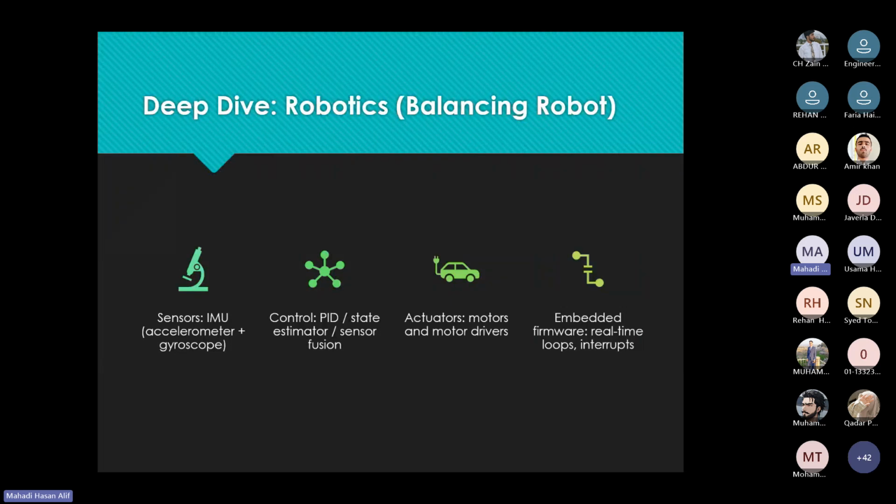The first kind is the values of the linear force on three axes, x, y, z, and the second is the velocity in the rotational axes, x, y, z again. So you get 3 plus 3, total 6 data, and depending on the frequency you're using, maybe 1 kilohertz, it means 1000 times 6, 6000 data every second.